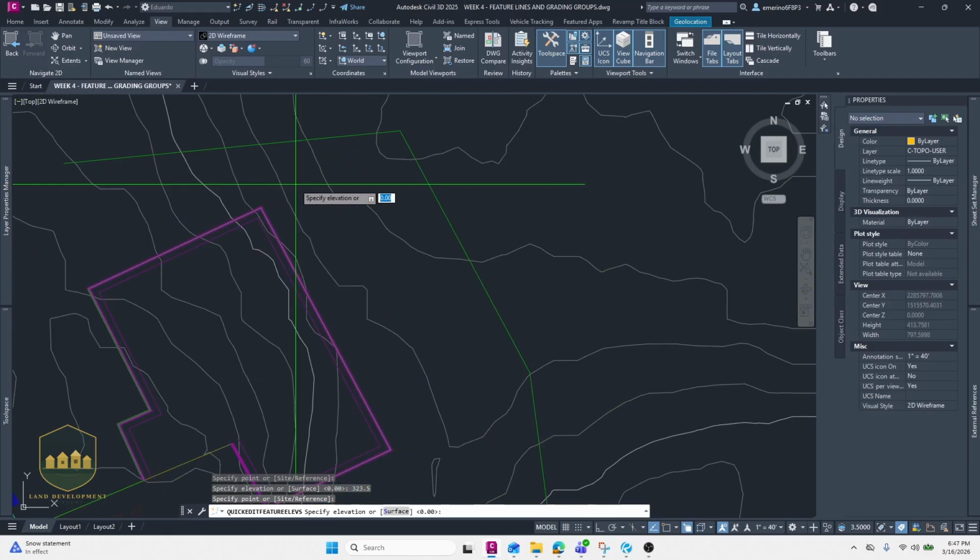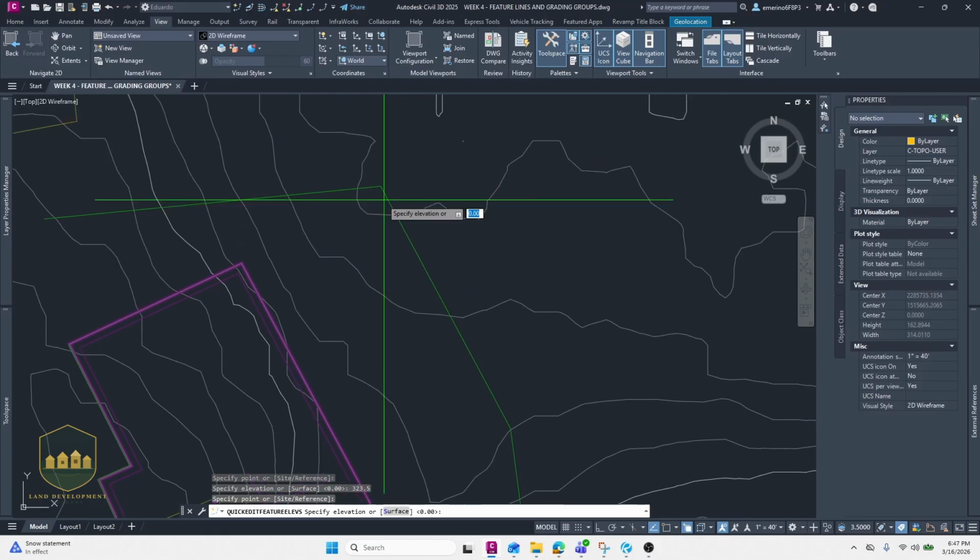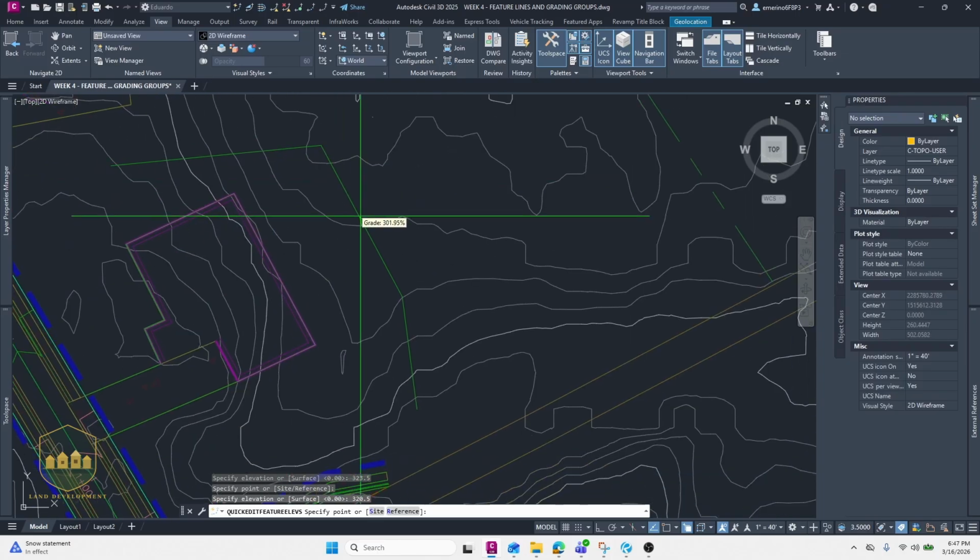I'm picturing here, I would like about a 3-foot elevation difference. I think for 62 feet, that's pretty good. It'll feel nice. You're walking outside and it's a pretty flat backyard. So the elevation will be 320.5. You have a nice 5% slope. I'm just going to go ahead and do 0.